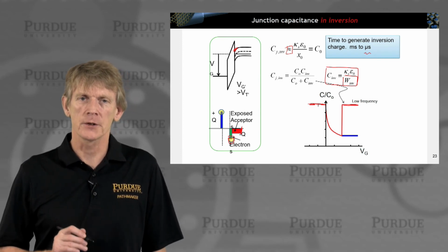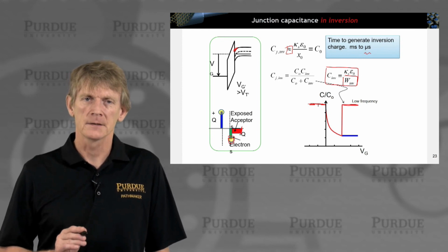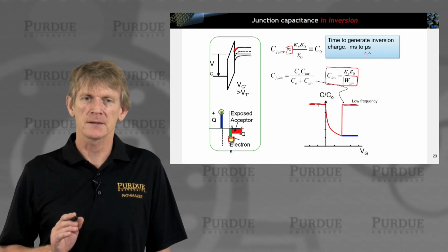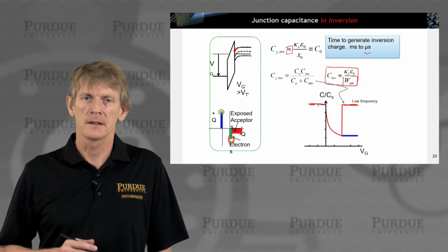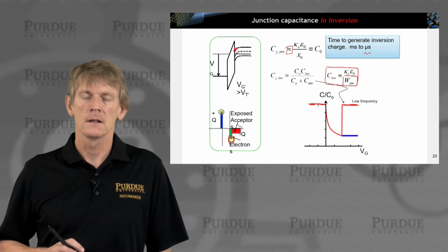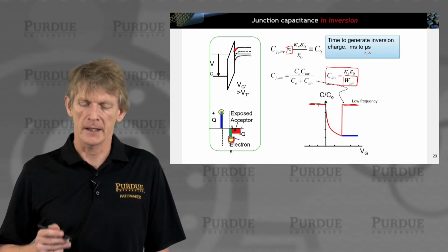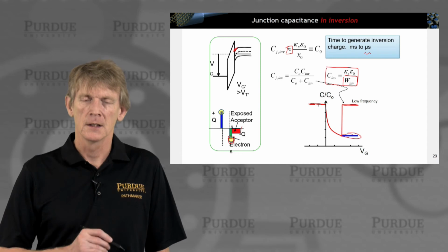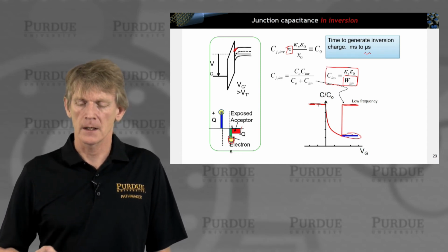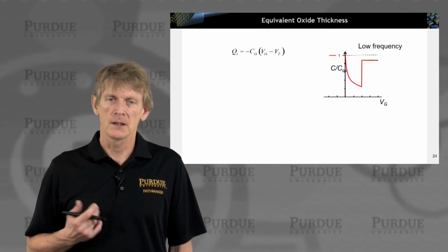There will be inversion charge. There is a channel of charge, but you will not add or subtract charges fast enough to follow in that inversion layer, but you will have to do that here at the depletion area. And if that's the case, we're going back to the mode where we have a depletion behavior in the semiconductor. Okay, so that's where we're going now in the low frequency response.